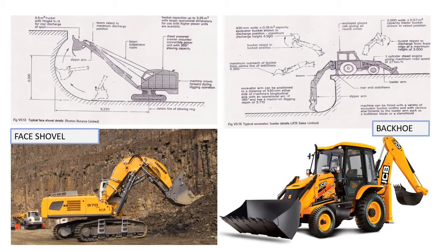Next, we have face shovels. These machines are sometimes called loaders or loader shovels, and their primary function is to scoop up loose materials in the front-mounted bucket, elevate the bucket, and maneuver into a position to deposit the loose material into an attendant transport vehicle. Tractor shovels are driven towards the pile of loose material, and the machine will enable the bucket to be filled. Both track and wheel versions are available, the track format being more suitable for wet and uneven ground conditions than the wheel tractor shovel, which has greater speed and maneuvering capabilities.